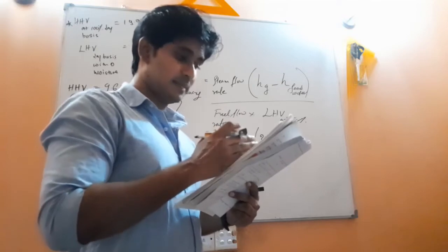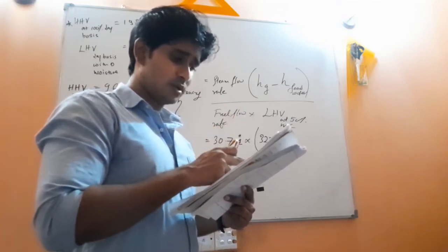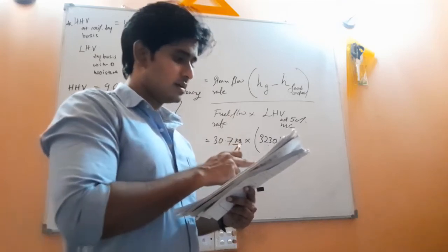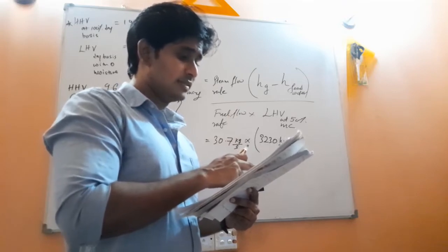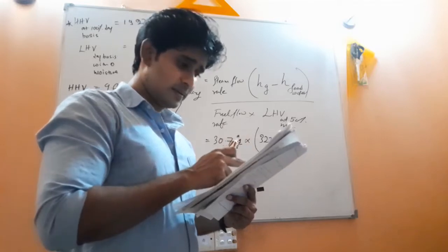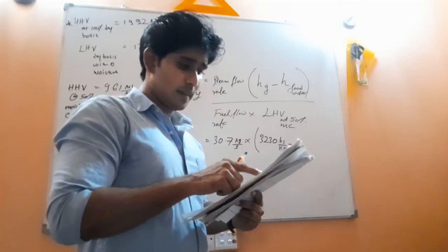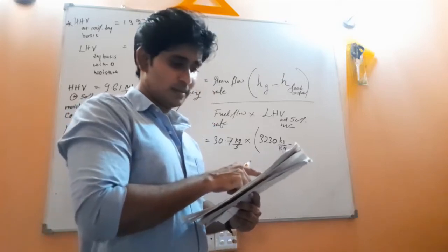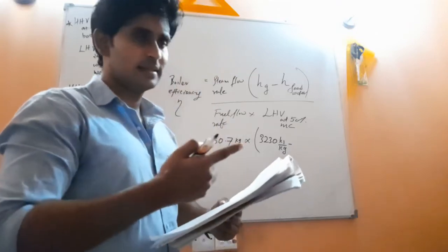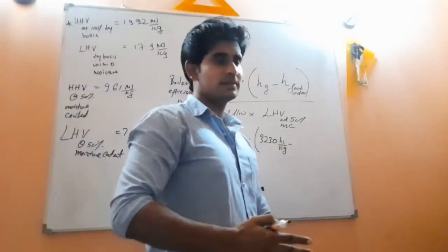Steam after the turbines is brought to sugar mill evaporators where the steam condenses to water. At the end also they have mentioned the condensate is brought back to the boiler. That means they are again sending that condensate as feed water. That means the condition of the feed water is given.